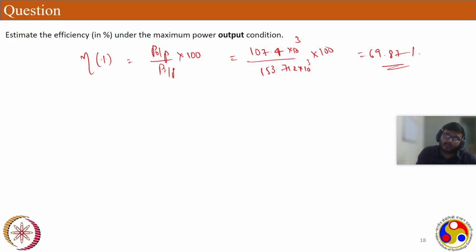Again, this is because of the 1 ohm resistance that is present in the synchronous impedance of the machine. So it's not very practical. That's why we're getting very low efficiency. Usually, it's not in that range. It's usually of the order of 10 to 100 times less than the reactance of the machine.